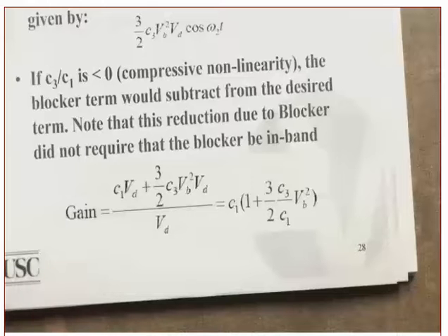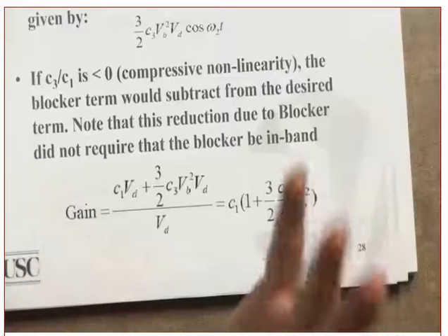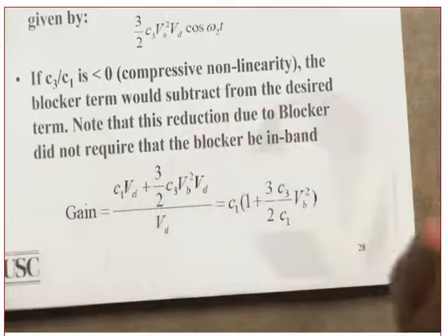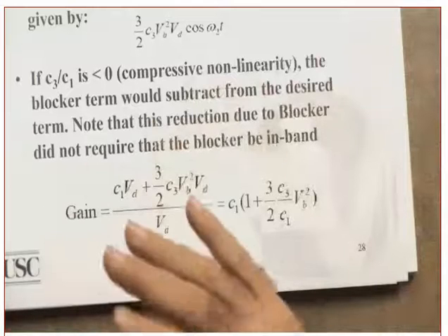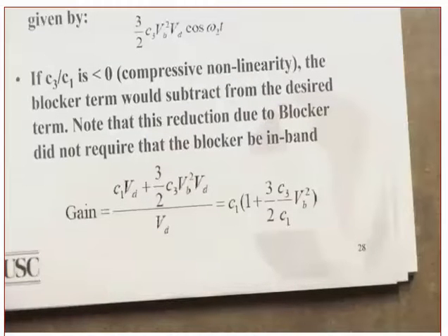First of all, do you understand what blocking of a receiver means? It is not going to be able to recognize there is a desired signal. Why? Because the amplifier is no longer an amplifier, it's now a compressor. Are you following me on that? And the desired signal is weak to begin with. So if you compress it, it will become even weaker.